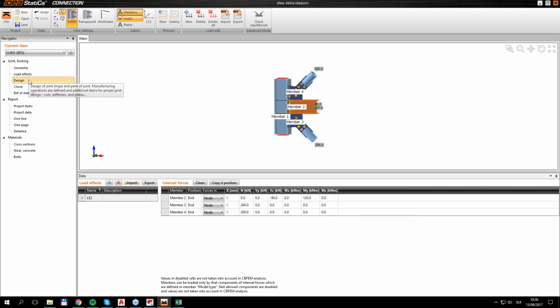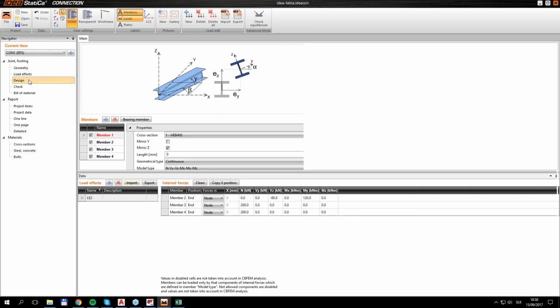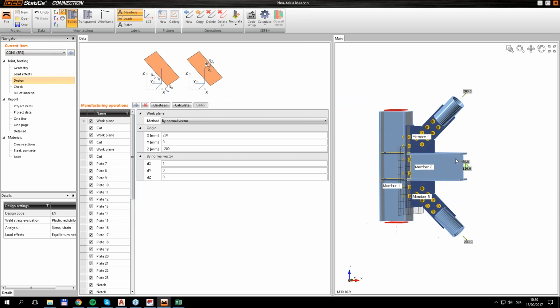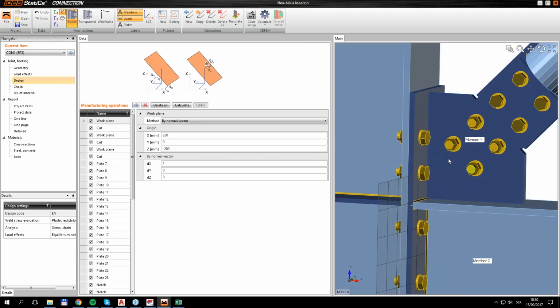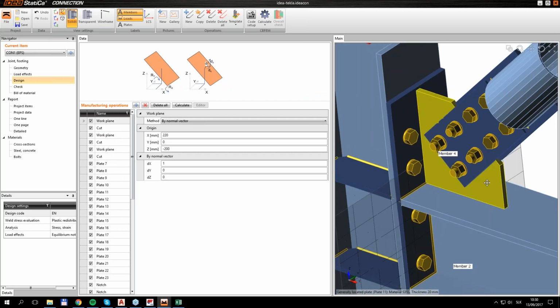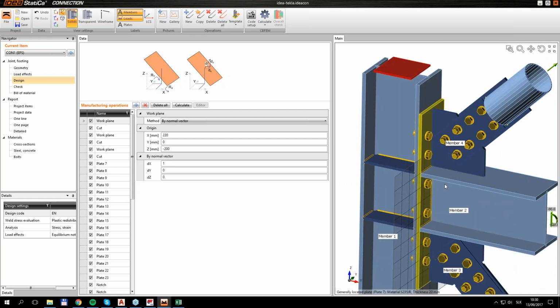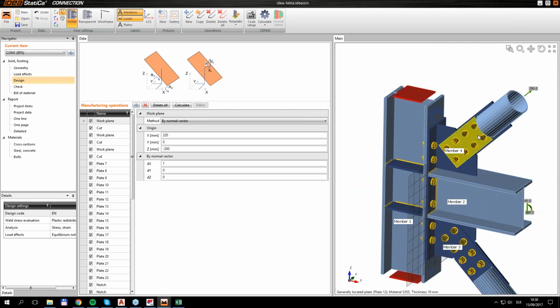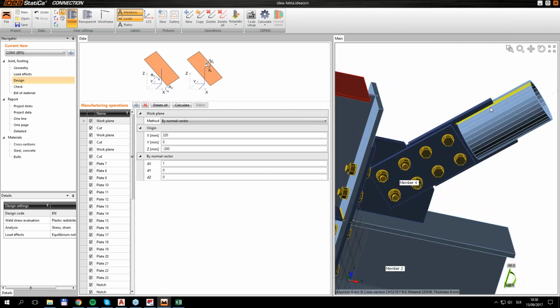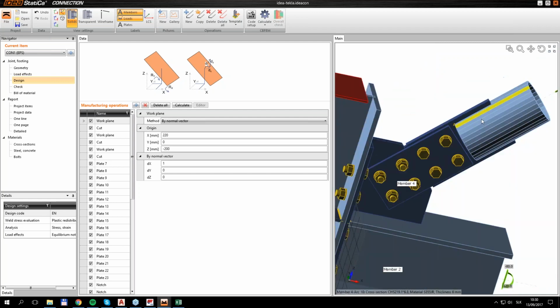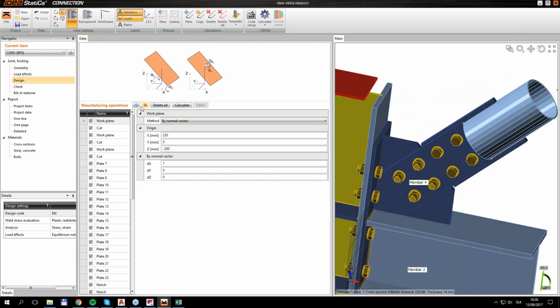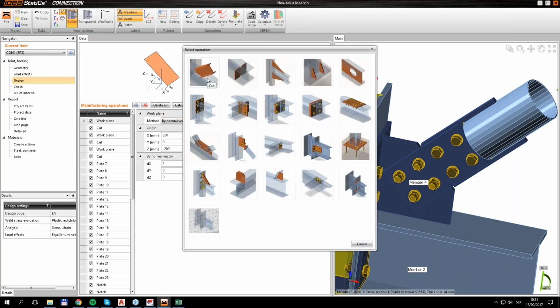And we omitted a few things in Tekla Structures. It happens sometimes. As you can see, these connecting plates are not connected to the end plate and to member 2. Also, these members are not welded properly. So let's just place a few cuts.